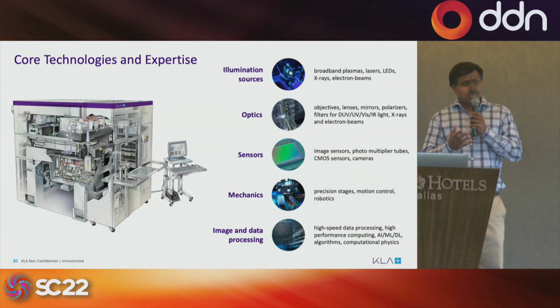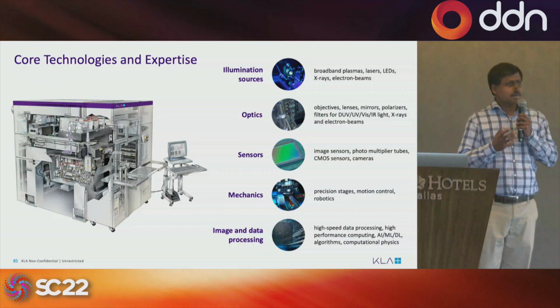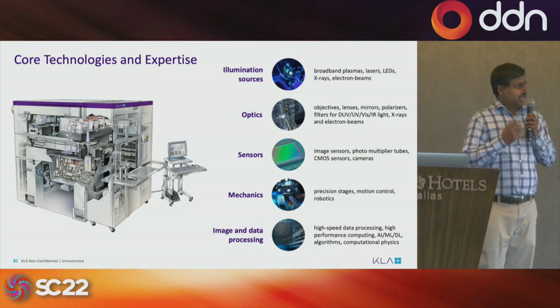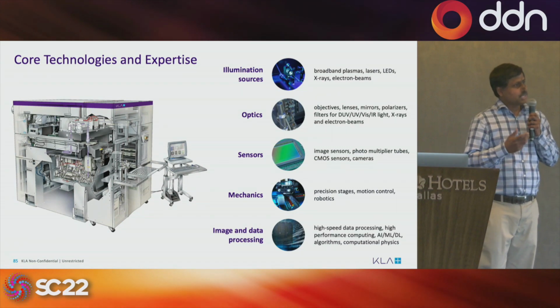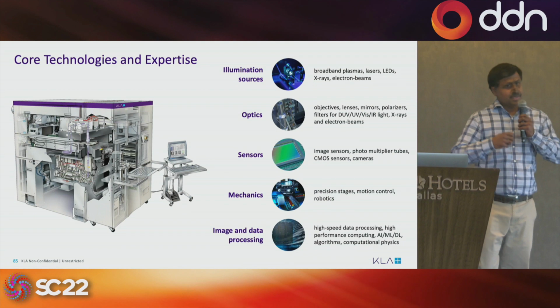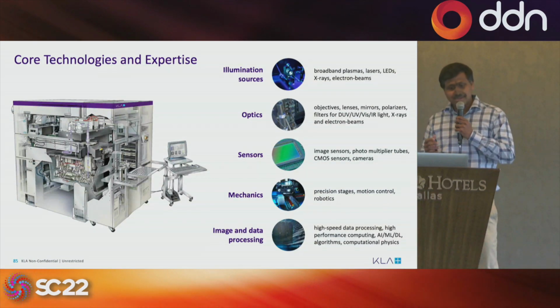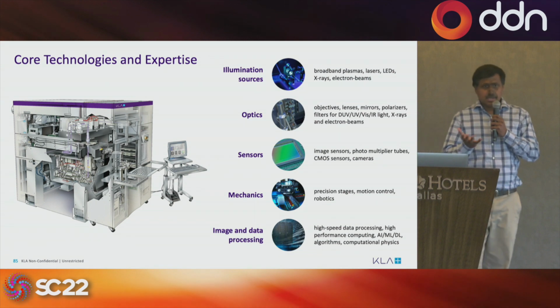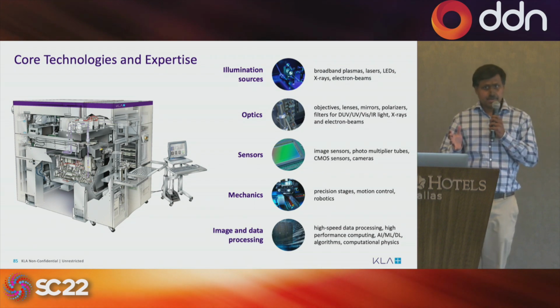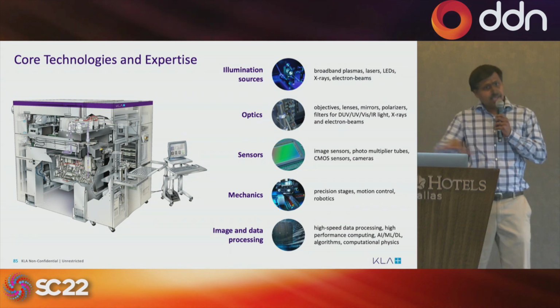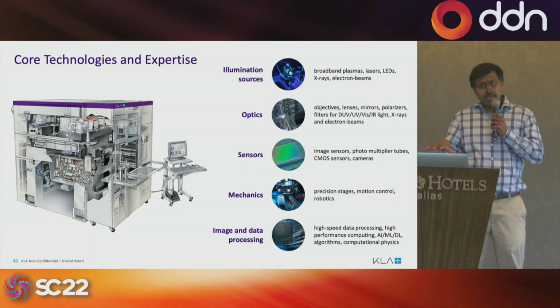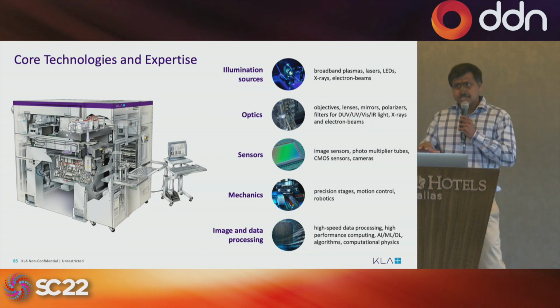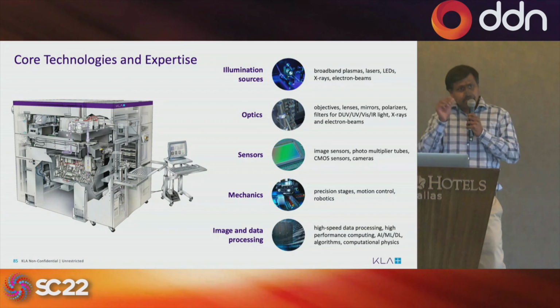And what we use is a laser pump, creating a fusion inside the bulb, and we need to make sure the bulb doesn't explode. That's our light source. And the stage on which you place this wafer is a really high-speed, automated, no vibration stage, and it has to be very precise.